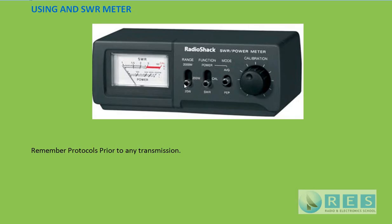That is actually not part of the SWR meter. You don't need to use that. This control is simply whether we want to measure average power or peak power. So these two really don't have anything to do with the functioning of the SWR meter. If you want to use power, you put this switch onto power, and then this is a power meter.